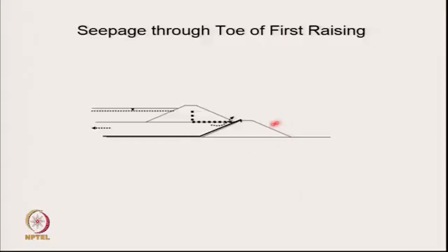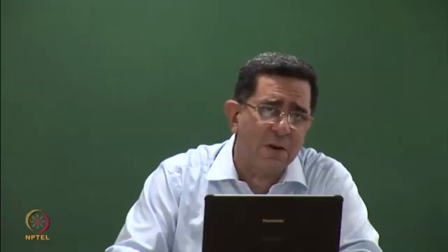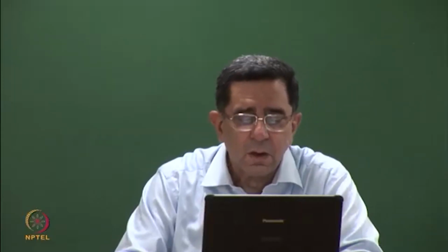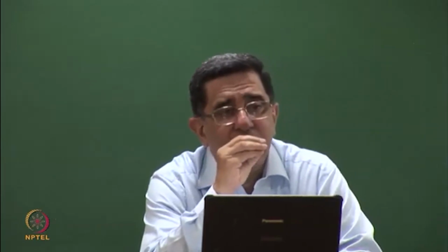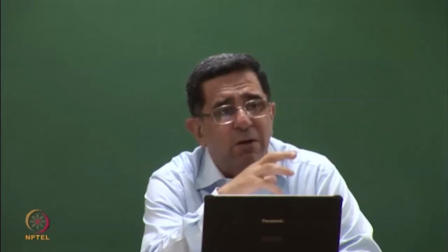This dike is not having any seepage. Why? Because the liner is functional. But this dike doesn't have a liner. So water can come out through this. So this starts to create stability problems. So the only way to put a liner in a slurry pond is also to have bottom drainage.